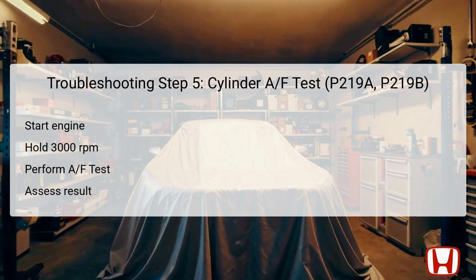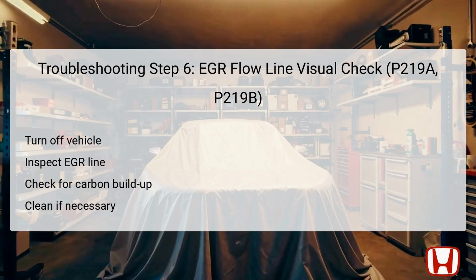Should the result not be satisfactory, the next logical step in troubleshooting should be pursued to identify any ongoing concerns causing air-fuel discrepancies. Step 6 involves visually inspecting the exhaust gas recirculation EGR line, focusing on potential blockages that could contribute to the air-fuel anomaly. Begin this step by ensuring the vehicle is turned off. Next, examine the EGR line for carbon deposits or sludge, which can impede proper exhaust flow and affect emission controls.